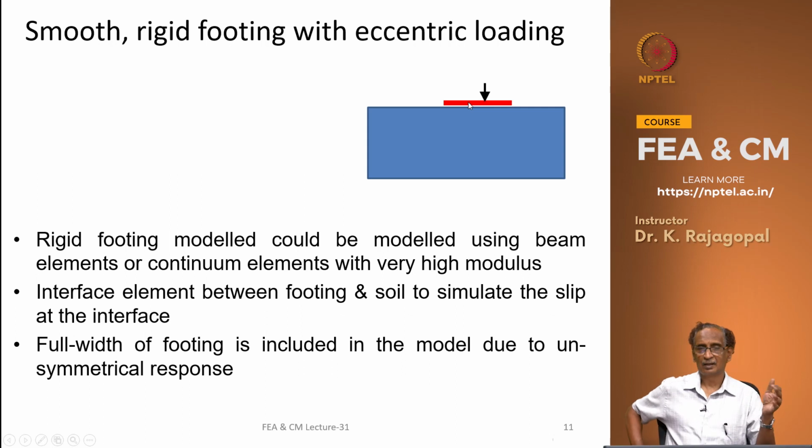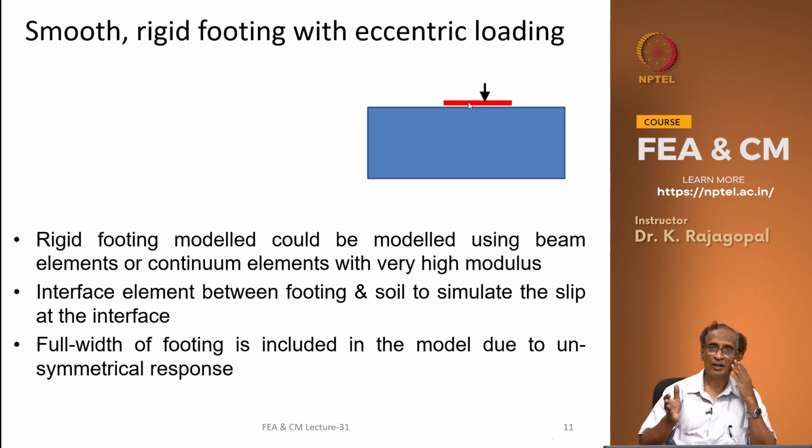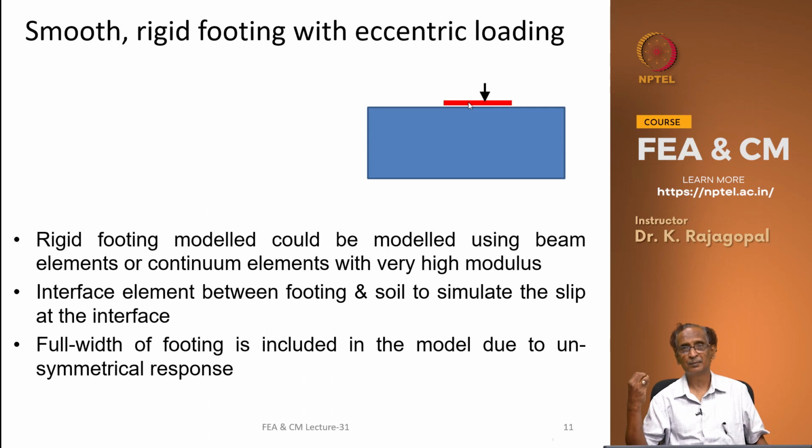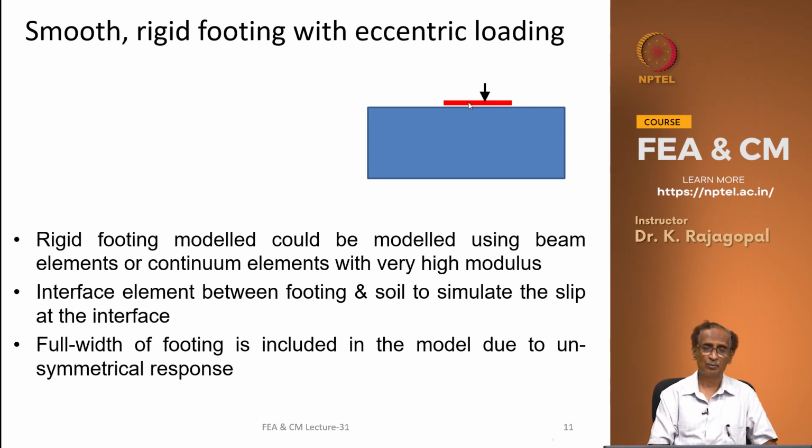But I do not suggest using that because that will complicate the analysis, and that will actually spoil the banded nature of the stiffness matrix, and then you end up spending a lot of time in doing the computations. Only for small problems you can use the constraint option, but for a large problem you better use a rigid element like either a beam element or a continuum.